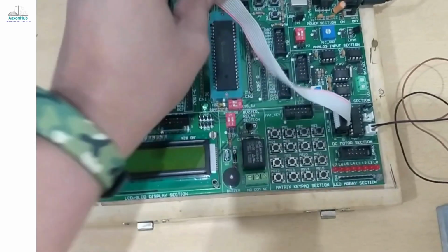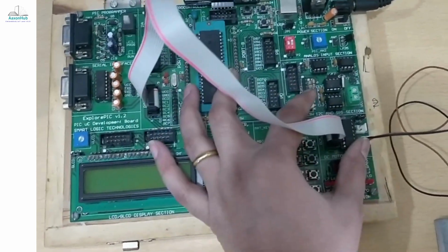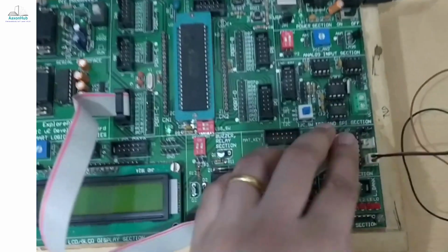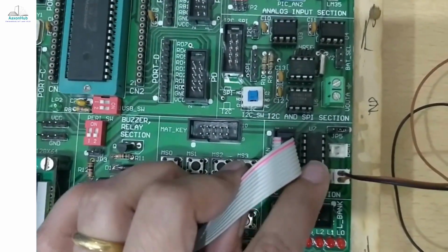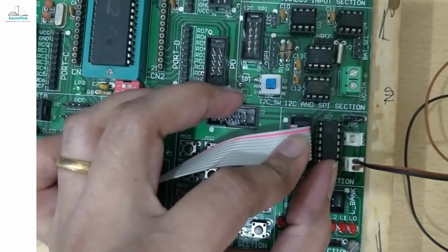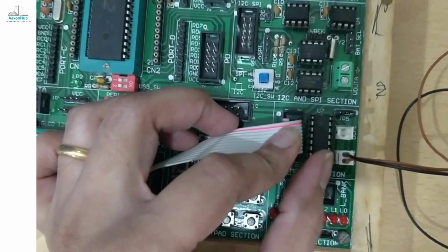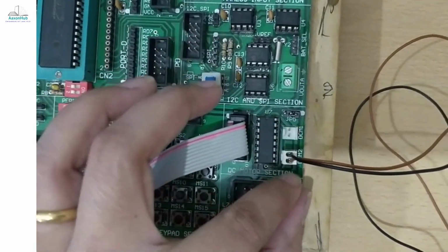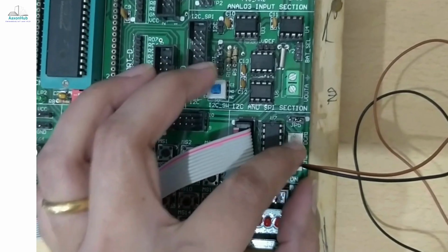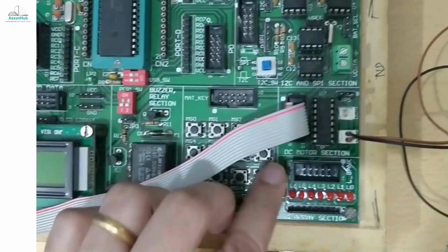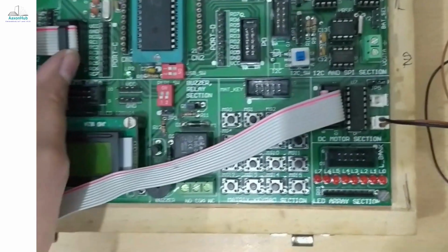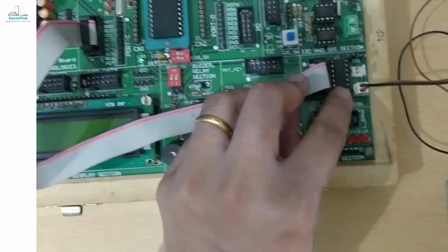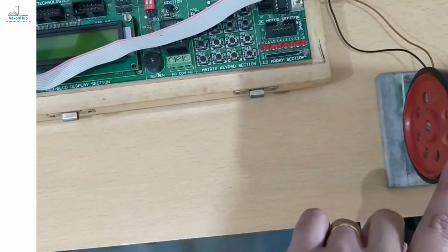One FRC cable is needed, because we are connecting this DC motor using this particular port C. So here is your motor driver. This L293D motor driver circuitry is there, where 2 channels are given. You can connect it to this channel or to this channel, so at a time 2 motors you can run using this. This motor driver is given in this DC motor section. So we are connecting it from one of the ports to this driver circuitry, and from the driver circuitry you are connecting to the DC motor.